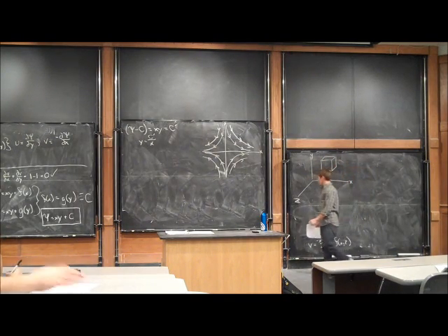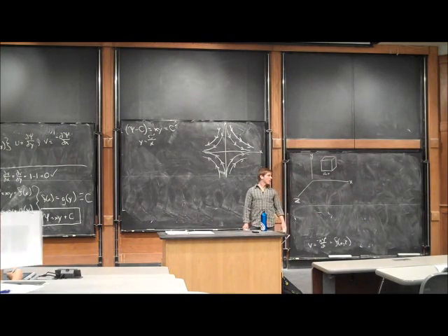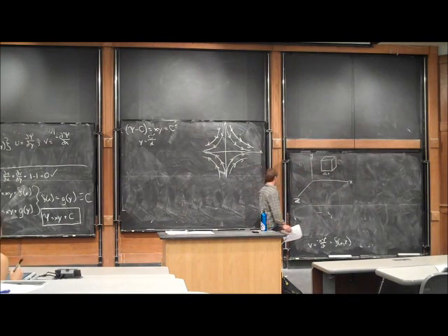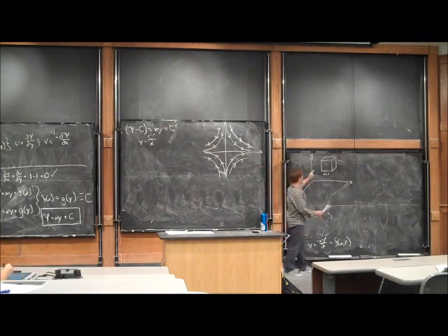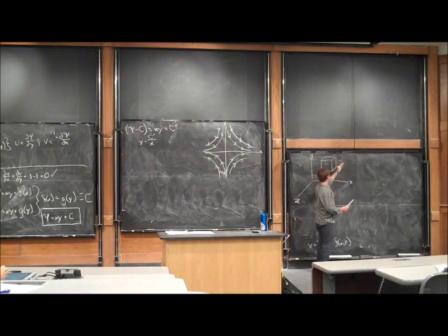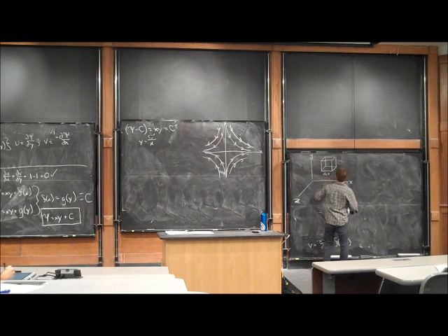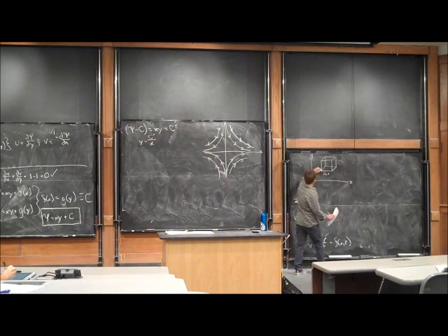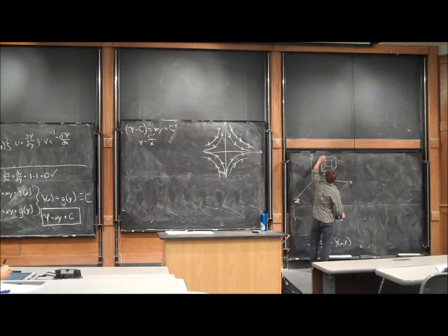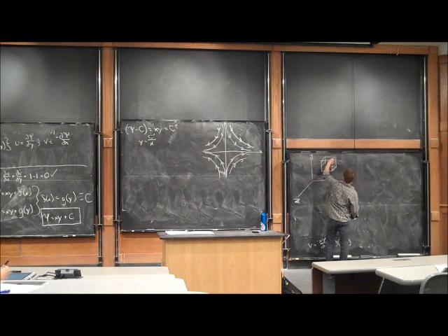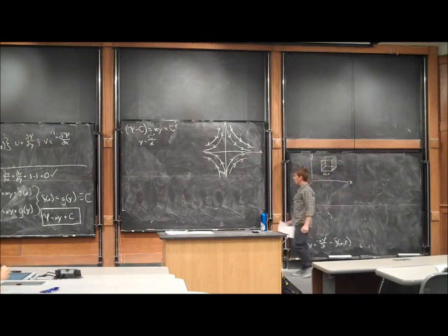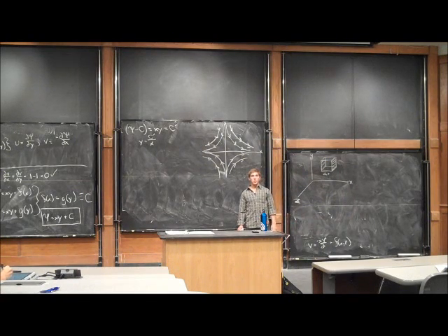It's a lot easier to visualize if we take it one component at a time. So it's a submerged fluid element, so we have a pressure acting on this face and a pressure acting on this face, this back face here. So I'm looking in the x direction, I need to look at the forces acting here and the forces acting here, and equate those to the acceleration of that fluid element in the x direction.